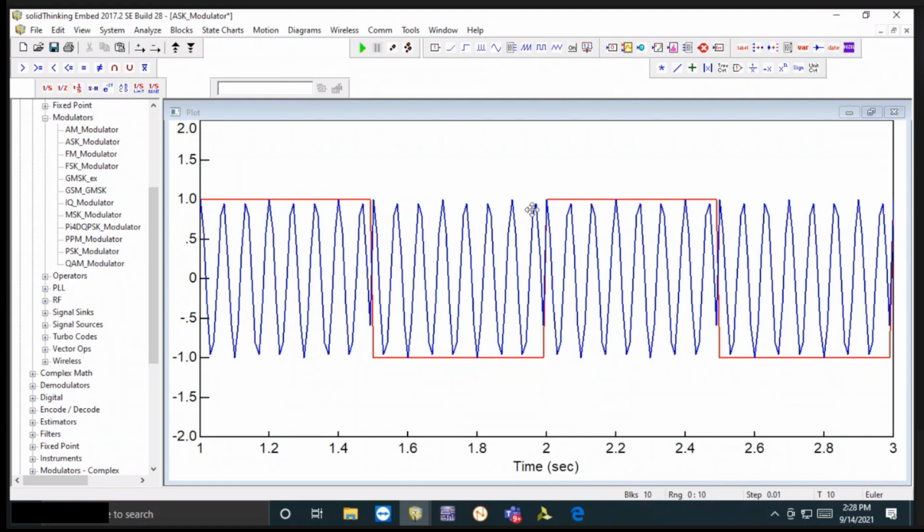So in this complete one cycle of the carrier signal, whenever it meets with the message signal, when there is a transition, okay, from 1 to -1 or -1 to 1, it will immediately at that point only reflect the phase shift of 180 degree. That means it will be multiplied with -1 value. Okay, you already know the constellation diagram, right? So that we'll talk about when we'll deal with the QPSK. So right now we are talking about the PSK. First we'll discuss the FSK and then we'll go to the QPSK, right?